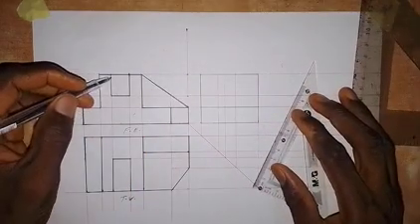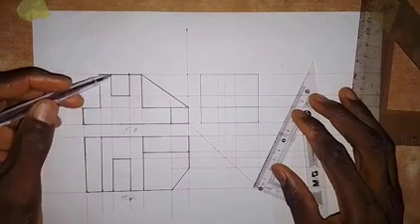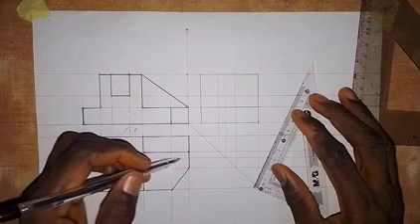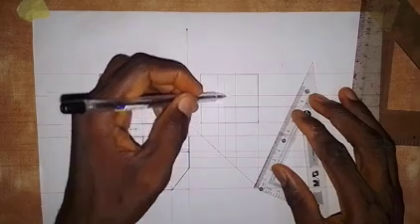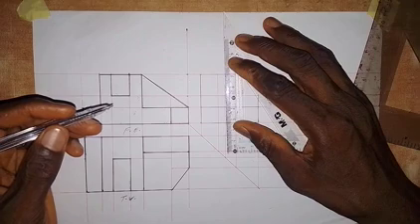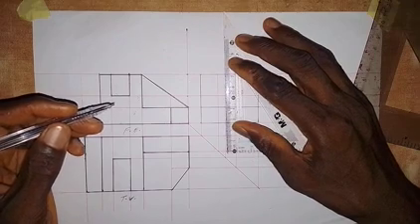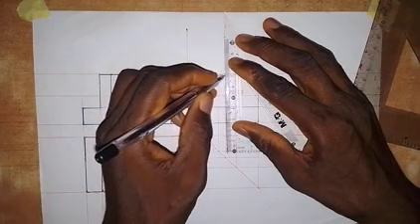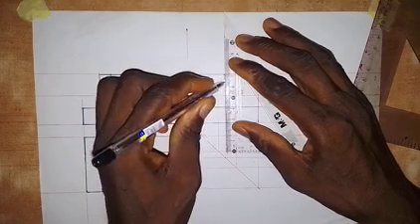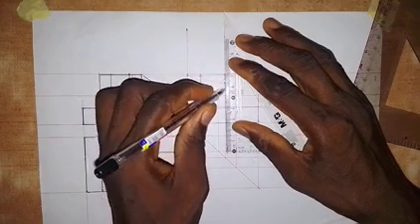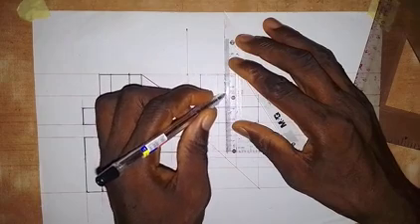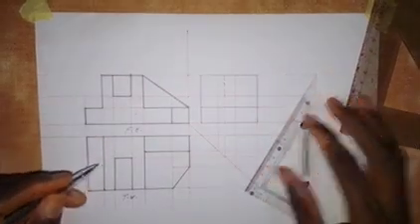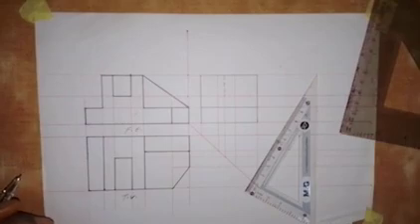And then on this part here, we are going to have a hidden line. So we have it at this point, going like this, up to this point. So we are going to have a short dashes line. So along this part, you have it here. So this line will be drawn with short dashes line that is hidden from us. Okay, so we have this one, and then from here to here, we bring out the shape.